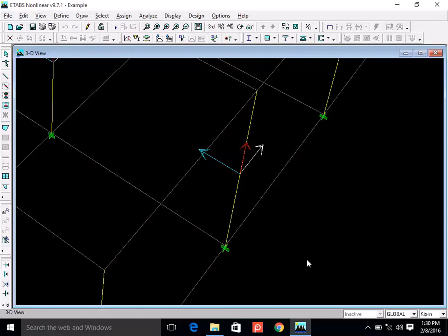Even if you neglect earthquake, for example, look at a corner column. A corner column has biaxial bending. Biaxial bending means movement about axis 2 as well as movement about axis 3. So both axes become relevant to shear force as well as bending moment.